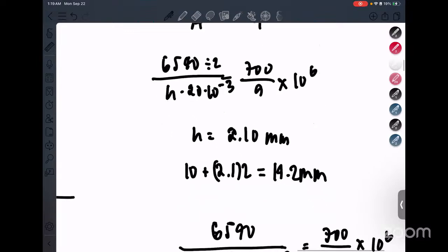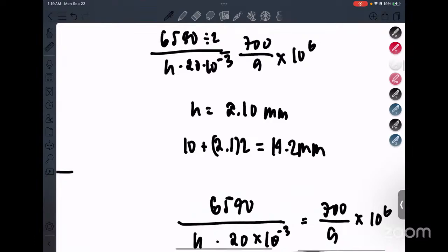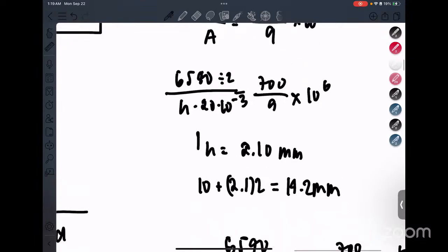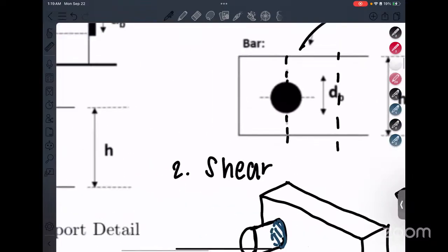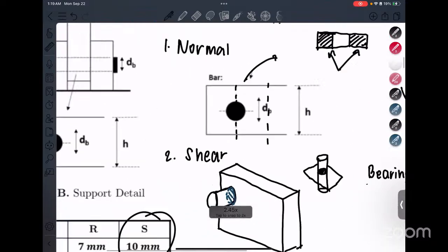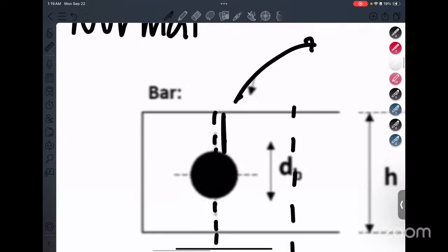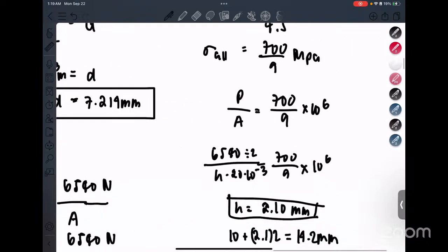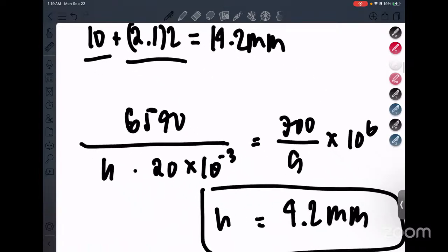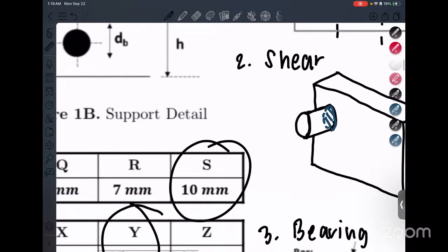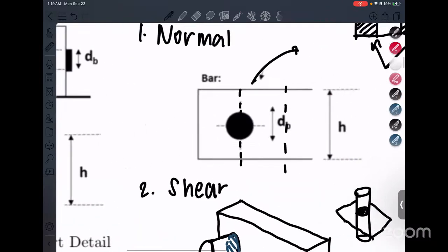Okay. Tapos this is 10 plus. So why isn't it ito lang? The reason is this 2.1 millimeters only measures this part. It only measures this part. So kailangan mo pa siyang i-doble plus add the diameter of the hole. So that's 10 millimeters plus 2.1 times 2, get 14.2. So that's for this part. The next naman is this part, which is more straightforward.